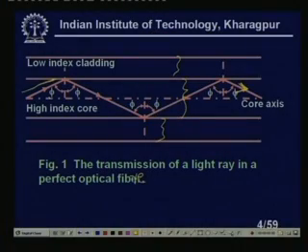So we have to arrange for total internal reflection, so that even if the fiber is not straight, if it is bent, light can travel through it. That is the idea of the optical fiber. Even though we know light travels only in a straight line, using total internal reflection we can see that in optical fibers light can go through a bent path. That is a tremendous advantage, and using that principle we have made many sensors.